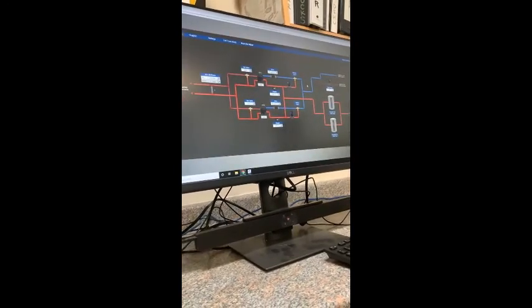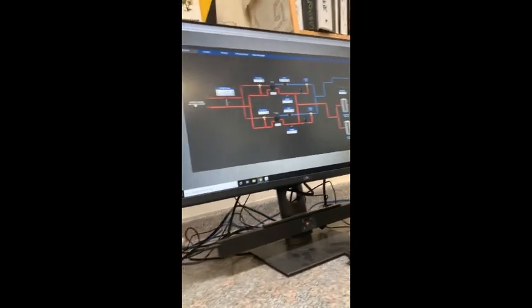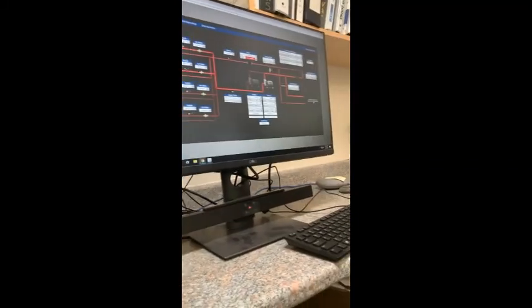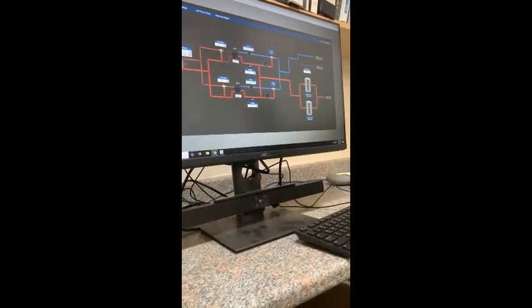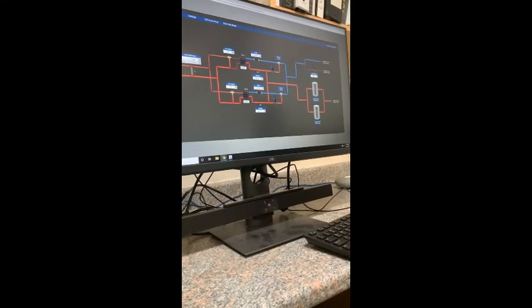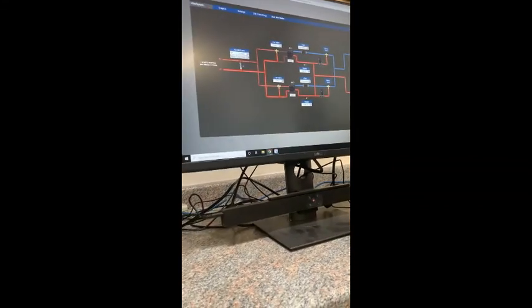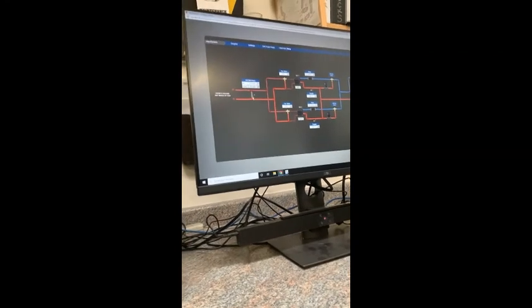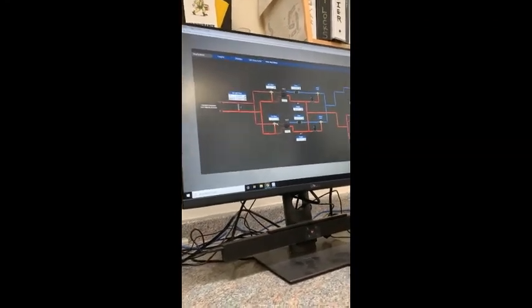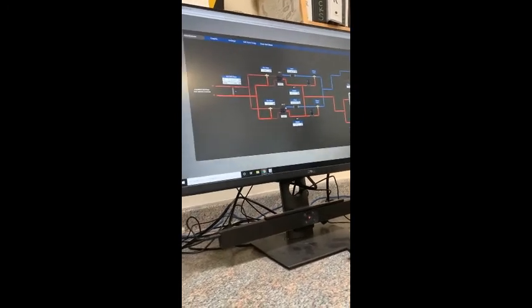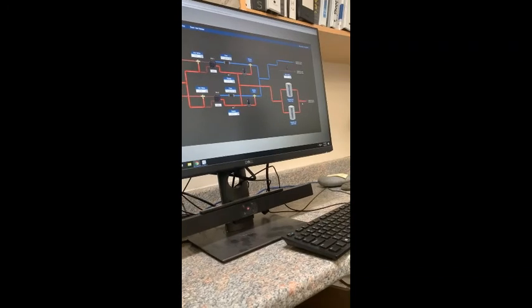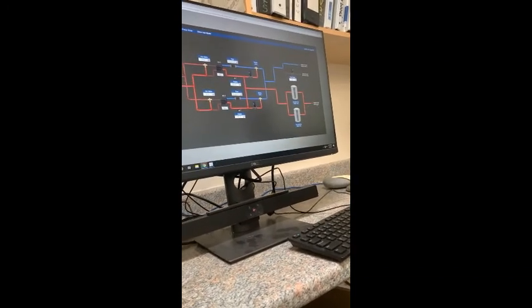From our other diagram, it shows the 2 psi and delta right there. From here, we can click back, and from here you can click over to, or you can click up here. It shows that bypass twice right there, right? Basically, it shows this DP sensor, differential pressure, I mean. We can see the heat valve. It'll open up if it needs to maintain this discharge temp, and it goes into these tanks and then out.